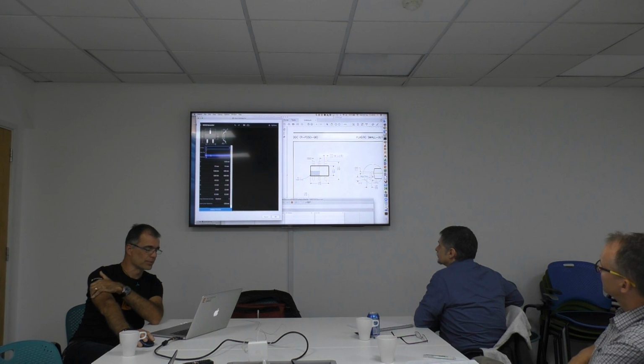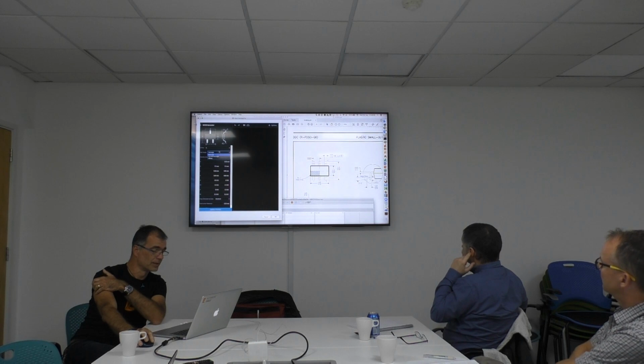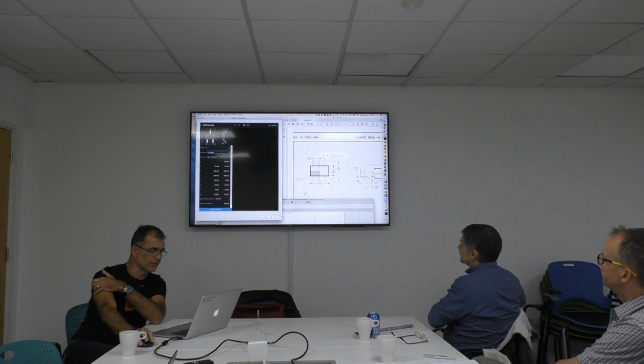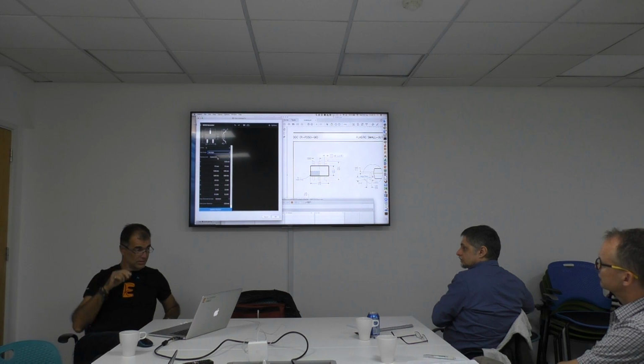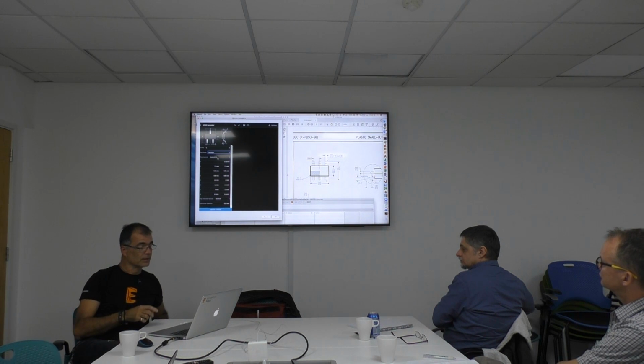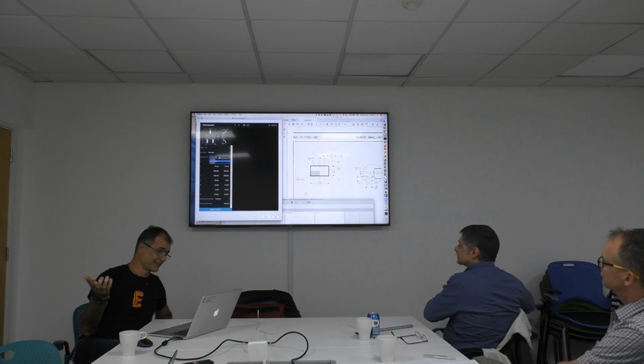You see I get the pre-selection. Then the pad shape, is it rectangle? It could also be rounded, it could be oblong, different shapes, also options. This is rectangle. The density level has to do with the IPC standards. There are 3 options, normal, most, and least, so it depends on the density of the board.